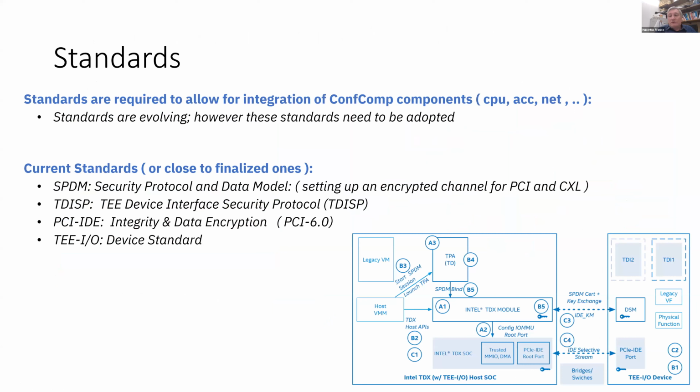That finally drives me to standards. In this area, as in any kind of advancement, people are jockeying ahead and implementing a solution, but then people start thinking about it and evolving these standards. The current standards we need to look at, and I listed four of them, are SPDM, which is a protocol and data model for setting up encrypted channels between end devices; TDISP, which is what a device needs to provide in order to be considered trustworthy; data encryption, which is now part of the standard in PCI; and the device standard for TEE-IO. My encouragement is to look at standards like these, because anybody implementing an accelerator has to at least conform to most of these issues, and that's the area where I'm currently working.